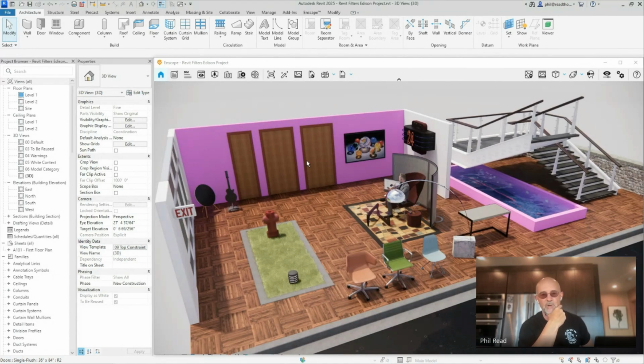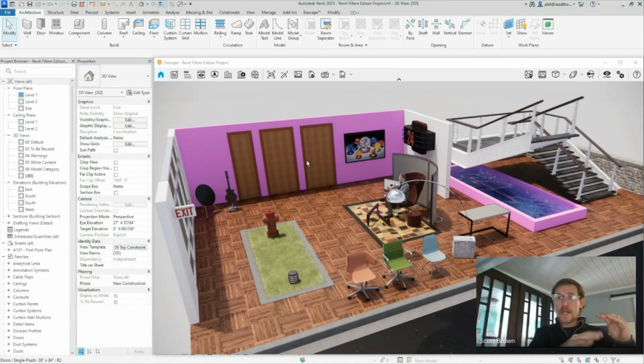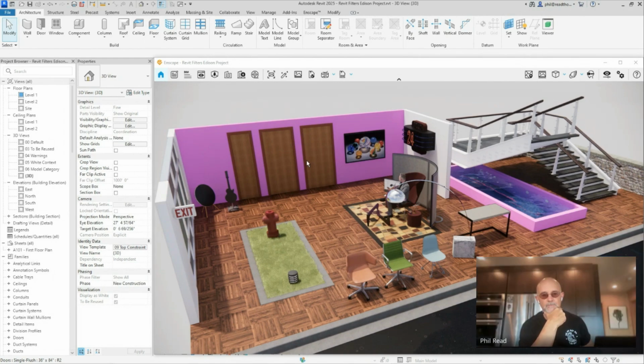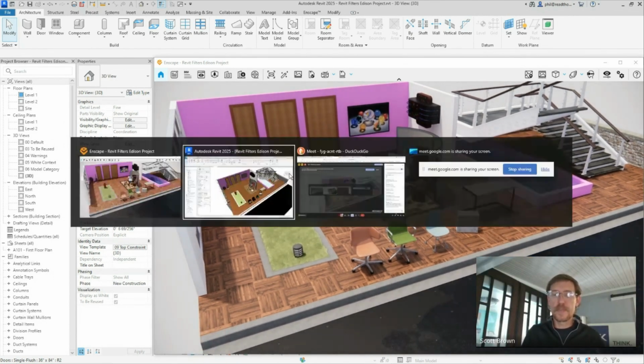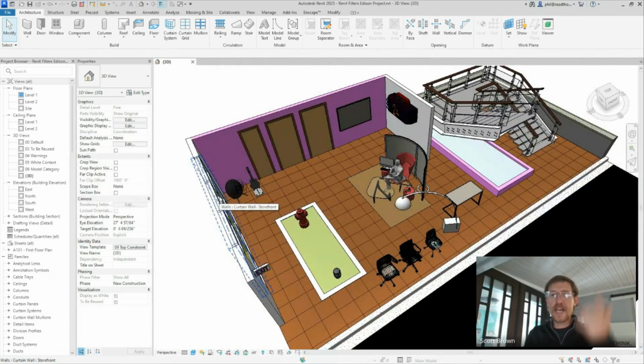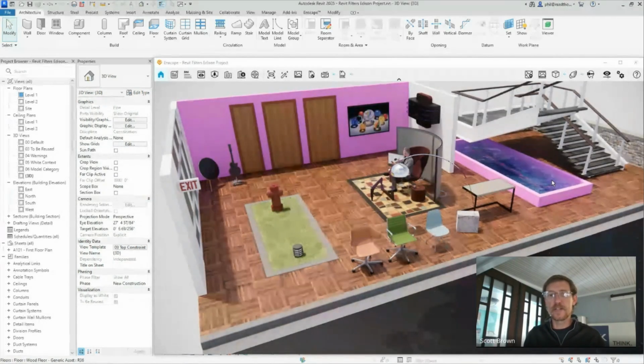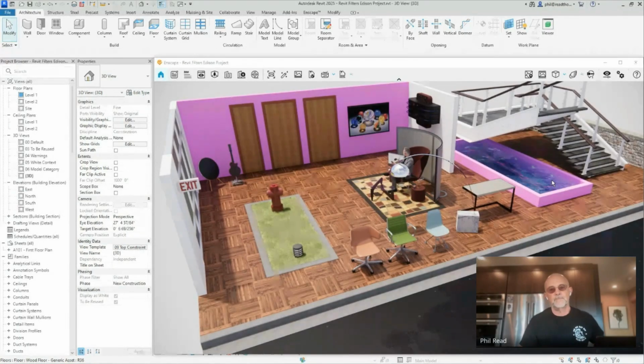And the parameter is an instance parameter. No, it's the normal top and bottom constraints in Revit, right? Every wall can have a base constraint with a positive or negative offset and a top constraint. And as long as those are from level 1 to level 2 minus something, or level 1 to level 1 plus something, it will report the proper height, the actual modeled height, I should say. Where just that attach tool just reports the original height. So like if your little 6-inch wall there, if you attach that to the ceiling above and pick on it in Revit, it's still going to tell you it's only a 6-inch tall wall. Gotcha. So you don't attach elements to the top because it's not going to give you the appropriate reporting value. It's going to mislead.